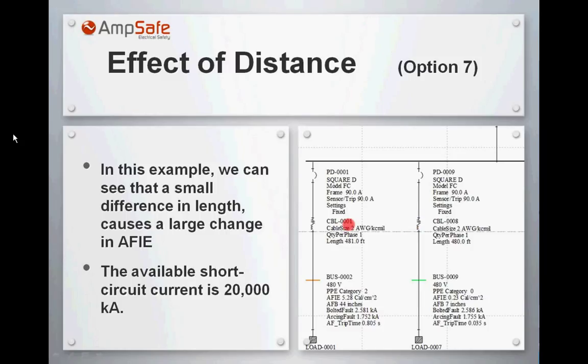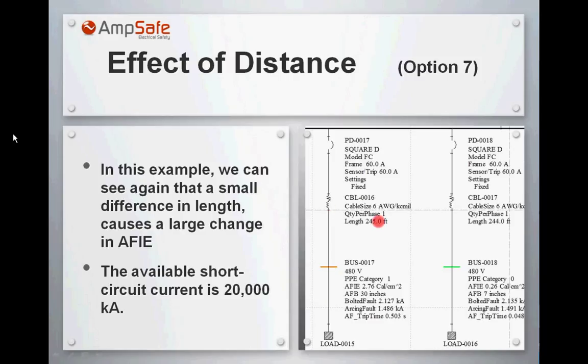Here's another case, 245 feet, and this is the worst possible case when you have circuit breakers lower than 100 amperes, like 60 ampere breakers. You don't need 400 feet, but about 244 to 245 feet for this particular case with this amount of short circuit current available, obviously. But still, those runs are pretty long for a small breaker. So it's not really a common issue that you're going to find, okay?